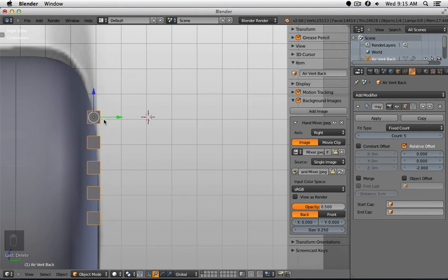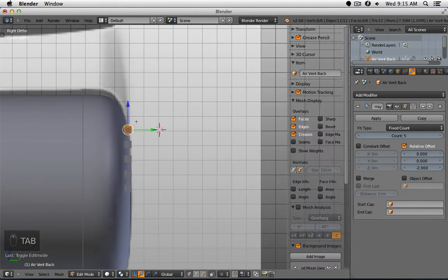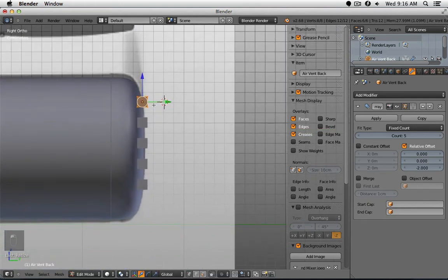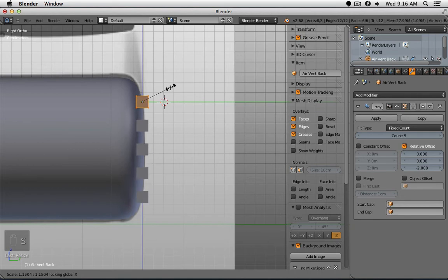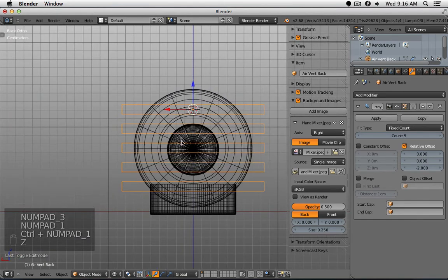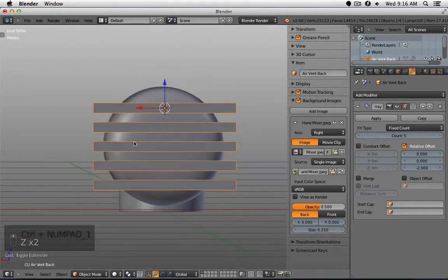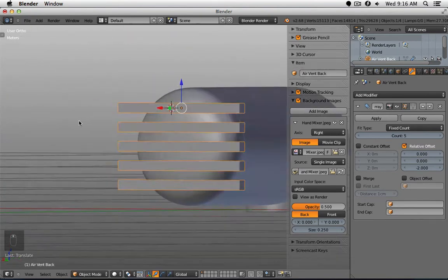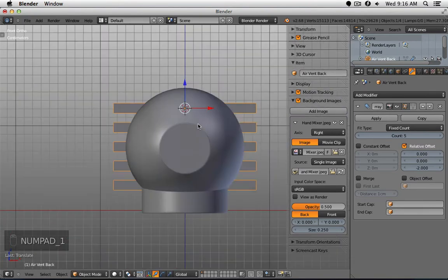The nice part is, if I go into edit mode and, for example, press S, Shift X, because I only want to scale along Z and Y, you see everything stays in relationship. So I have one master object I can scale, and everything else then follows. So, for example, I can move this one in a little bit. Okay.